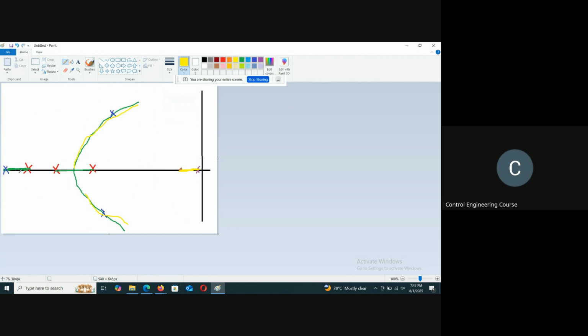Got it? Right. So beta should be really high so that the steady state error is controlled. But still, even if beta is high, these two together have to be much closer to the origin compared to the remaining guys here. Got it?